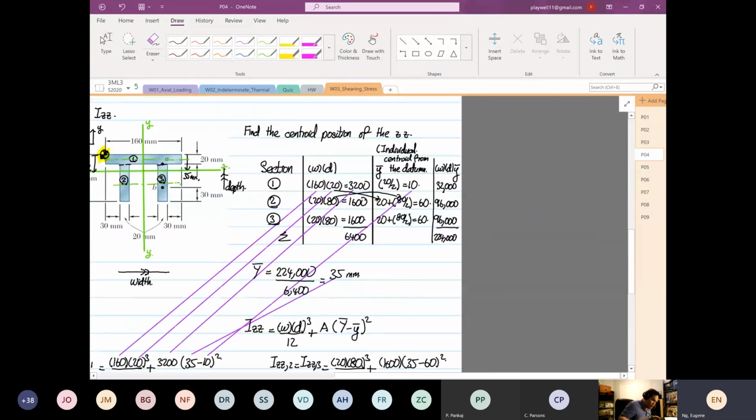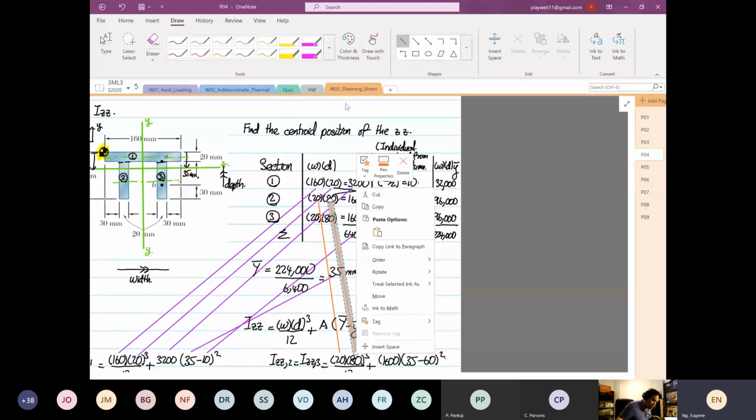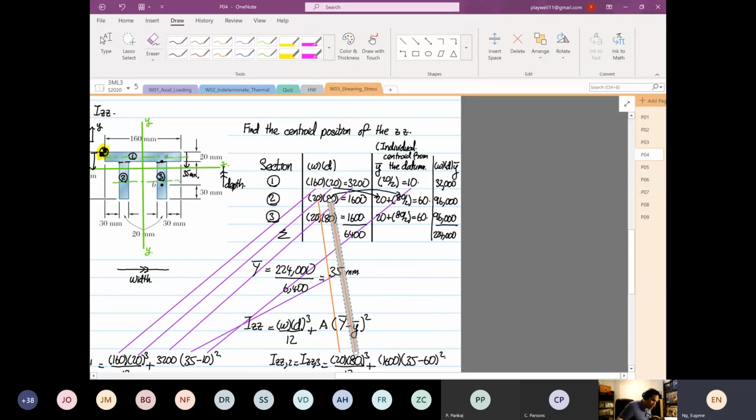Again, what you see down here, the sequences are the same. So this number will drop to here. This number will just drop to here, mindless. If you arrange your data, you can create a spreadsheet like what I do to calculate the second moment of area. This is simple geometry. You calculate where this comes to here, and finally this comes to here. Simple stuff. You will never make a mistake if you arrange your data that way.